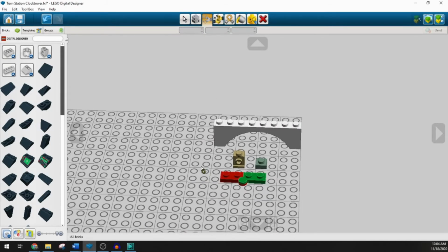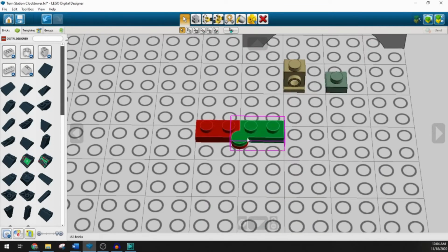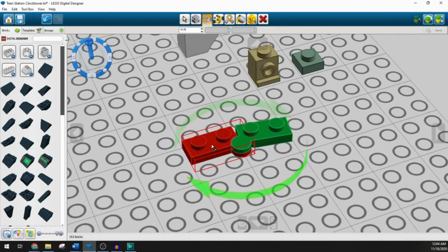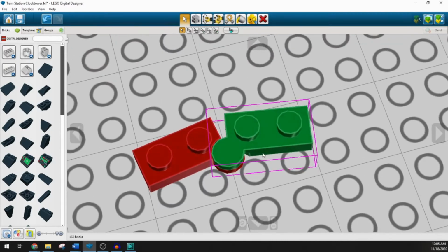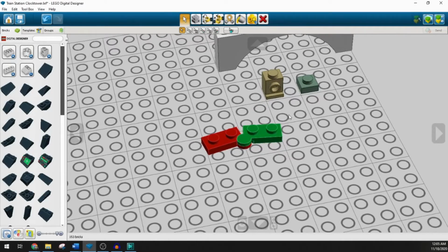But basically, we're going to start with this little hinge plate, and I'll center it up here. What you want to do is put this hinge at negative 9.75, angle that a little bit, and then put this hinge at negative 19.75, I think, 0.5. So we've got that kind of split right there, and I haven't done the math to see what the significance of those numbers are, but that's kind of what you need to do to get this result.